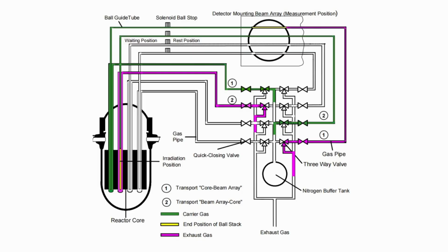Then there is the aeroball measurement system. These aeroballs are steel balls containing vanadium. The nitrogen gas driving medium transports these aeroballs inside the reactor pressure vessel. Inside the reactor core, these balls will get irradiated. After irradiation, these balls are retrieved and they are analyzed for the flux map distribution inside the reactor core.